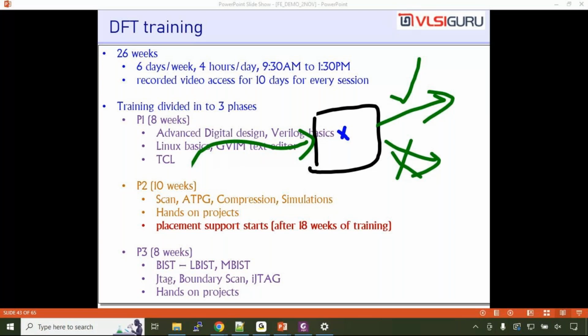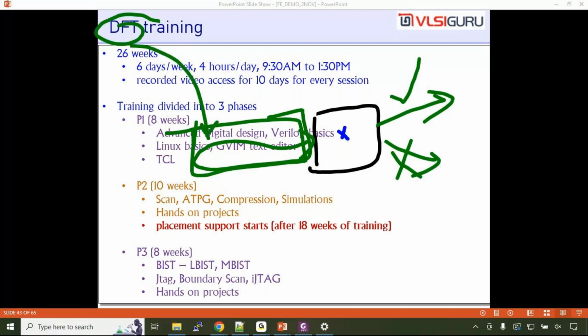The person who generates these inputs, what inputs to apply? Okay, let's say to check a laptop, do you randomly start banging the laptop? No, right? You start doing some meaningful operation, right? That pattern, how will you check the chip? That pattern is provided by the DFT engineer. They are called test vectors. The patterns are called what? Test vectors. Those vectors are generated by whom? DFT engineer. The DFT engineer gives them, these are used by the post silicon validation engineer and he checks it.